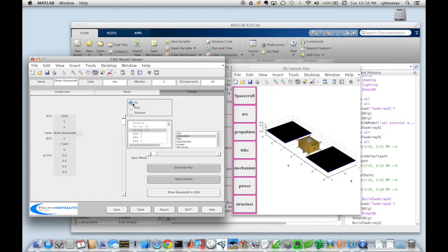Finally, we can view the spacecraft in orbit. In order for this window to work, you have to have provided an orbit location, or RECI, and an LVLH quaternion via the model metadata. We can see these defined on the left-hand side of the tab. This view also will light the planet using the sun ephemeris, and it will use today's date. When using it in a loop in a simulation, you can specify the actual date of interest.